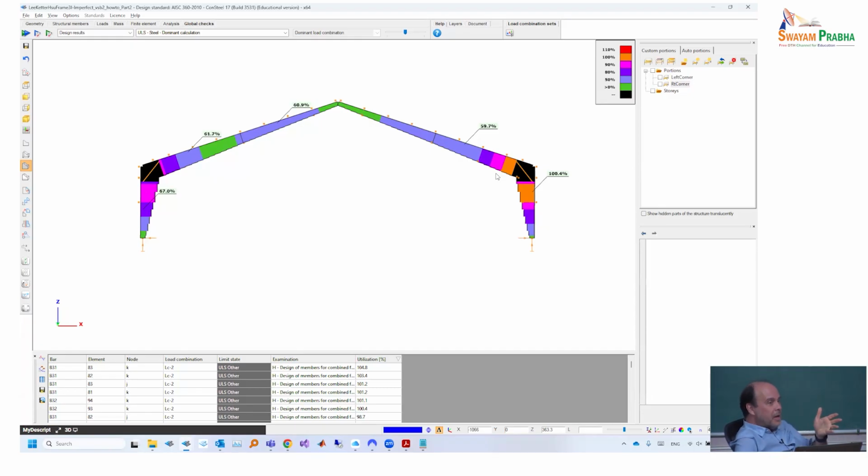Okay, obviously, even if we have a continuous connection between column to web, it's not a fixed end from LTB point of view, because that's the poor column by torsion who would need to provide the fixity, and its torsion resistance is close to zero, but it's not zero, and that's a huge difference if something is really zero or just small. And many, many small things together are producing a visible something.